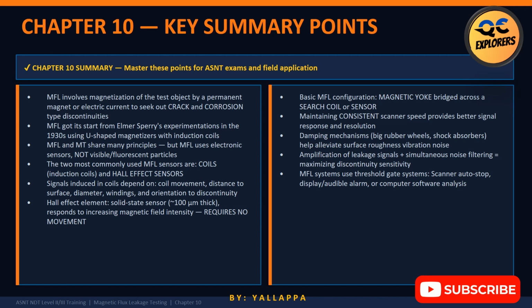Never forget that limitation. This question appears repeatedly in certification exams. Can MFL inspect aluminum heat exchanger tubing? No. Can MFL inspect carbon steel tank floors? Absolutely. Third, MFL originated from the work of Elmer Sperry in the 1930s. Remember this historical point.